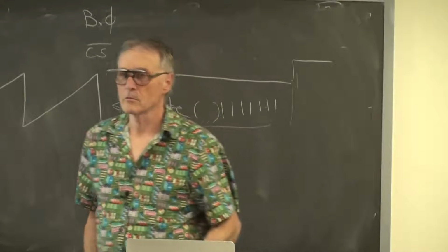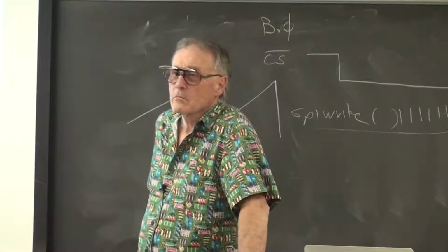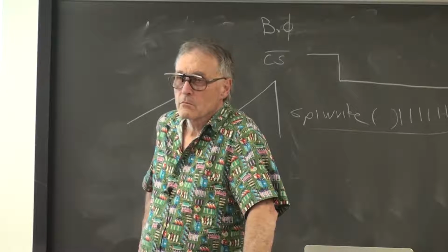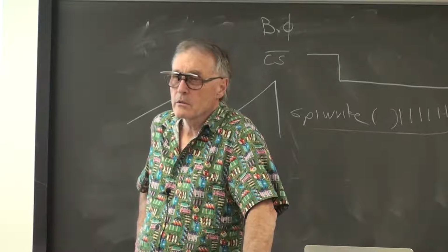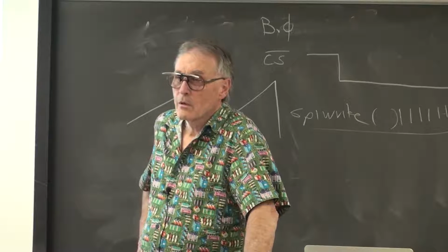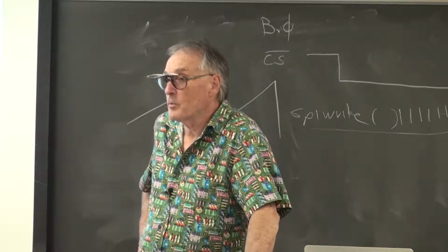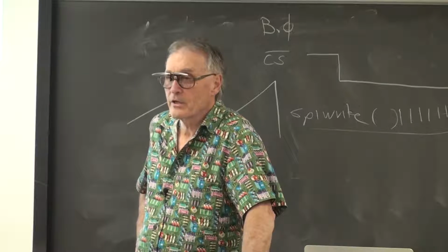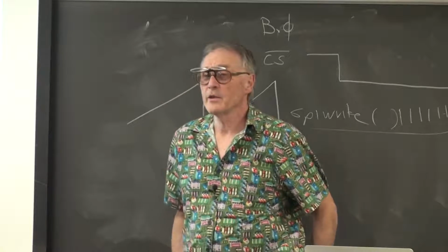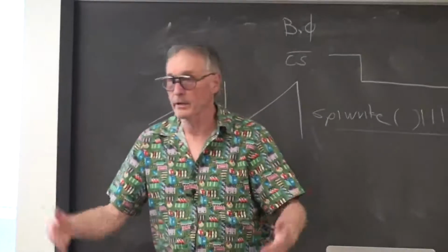Yes? Also for the SPI DAC, when I'm sending out information to one of the channels, I can hear some noise at another channel. Okay, what kind of noise? Periodic noise. Put it on the scope and show me, so we can look at the Fourier transform of it and see what it is. It could be clock noise. It could be that you're hearing some subharmonic of the clock because of a periodic output. I don't know without looking at it.